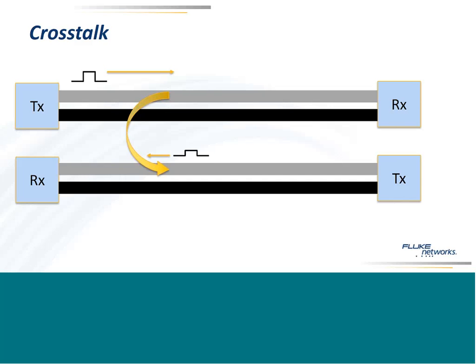Now the signal's smaller, of course, but as signals travel down the wire, they get a lot smaller. So the transmit signal could be 1,000 times bigger than the receive signal. So even a little bit of crosstalk can look like the guy at the other end is trying to talk to you. Of course, for those of you who are maybe over 40, you might recall being on phone calls some days where you could hear a faint conversation in the background of another person's phone call. It kind of screws you up. That's where the whole term and the name crosstalk came from.